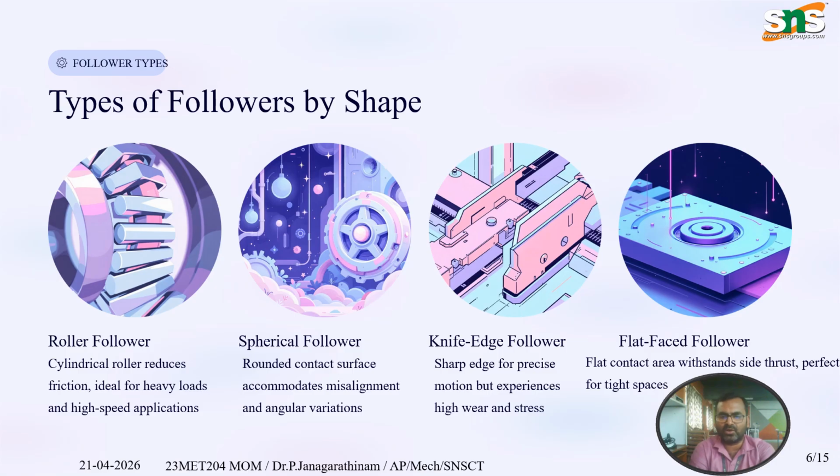The knife edge follower has a sharp edge for precise motion, but experiences high wear and stress. The spherical follower has a rounded contact surface, and the roller follower has a cylindrical roller that reduces friction, ideal for heavy load applications. The flat faced follower has a flat contact area and is used in tight spaces.